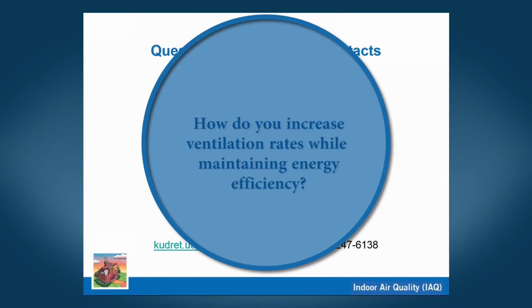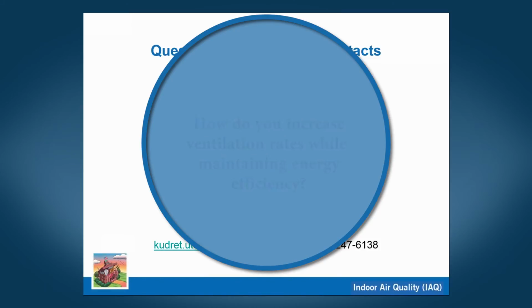So there are things that you can look at, and like Bill mentioned, CO2 sensors that can help you moving forward to make sure that you're properly ventilating the space. You're only putting in as much air as ASHRAE would recommend for certain square footage, and exhausting a certain amount of air, and so on. And of course, that's good whether you're trying to increase energy efficiency or open the outside ventilation. Either way, it's good to keep in the back of your mind.